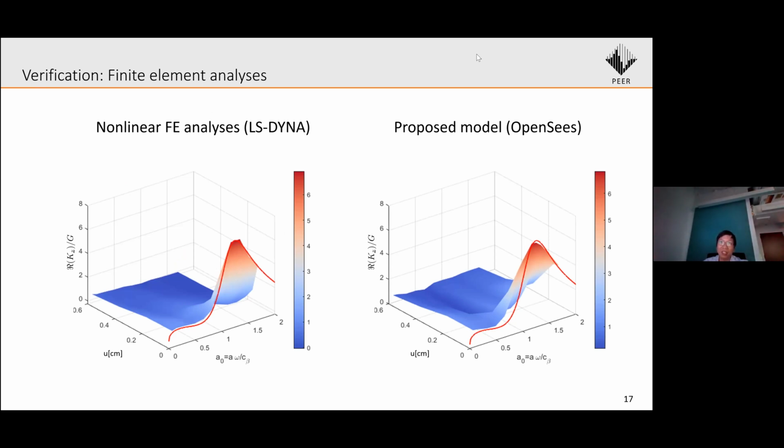in the elastic region. We can see that in the small displacement, the system is linear elastic, and the impedance follows the theoretical solutions. But when the displacement is larger, the nonlinear behavior appears, and the real part of the impedance, for example, the slope of the force displacement curve, decreases and reaches nearly zero when the ultimate resistance is reached. And again, we can see a good agreement between those two methods.